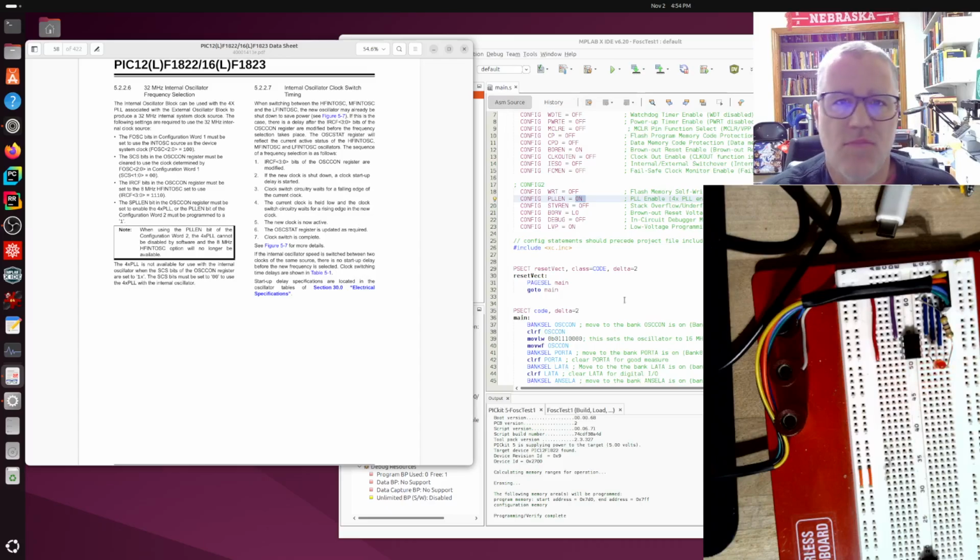Many times it doesn't really matter, and for most of the stuff it doesn't. We're going to be going into a segment here using the pulse width modulation, and you do want to change the clock speeds, because that'll help you control the frequency of the pulse width modulation.